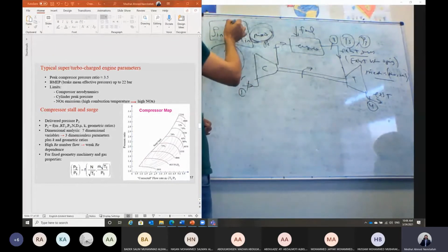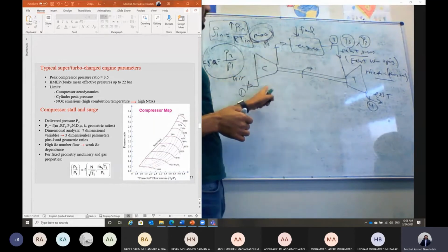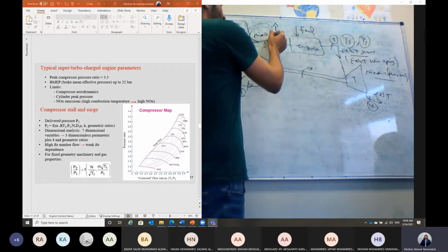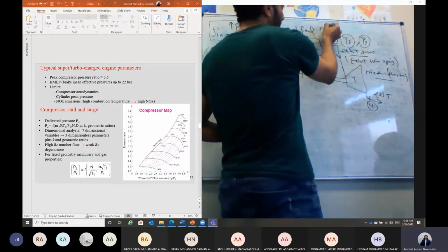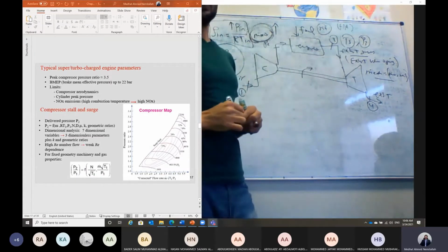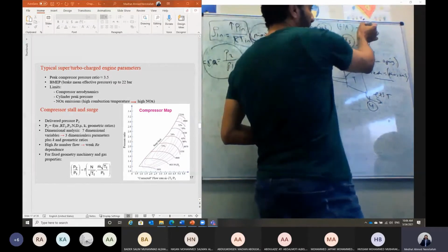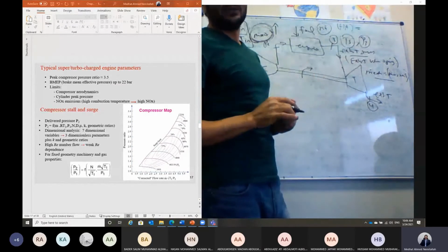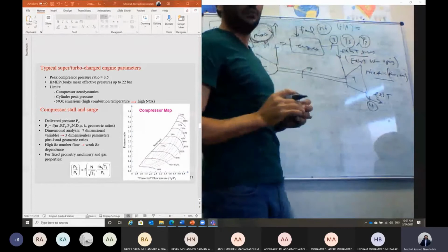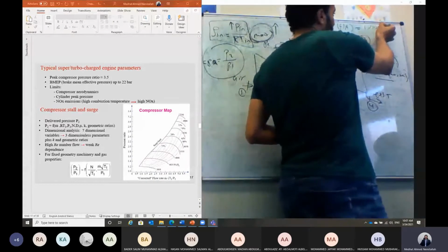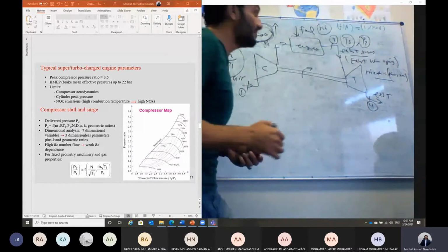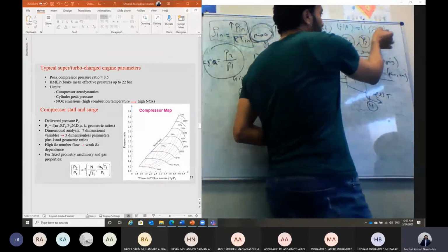So if we are able to raise the pressure at the intake manifold of the engine through the compressor, then in this case we can raise the mass flow rate of air. And based on this mass flow rate of air, the engine will decide the corresponding mass flow rate of fuel that will achieve a certain value of fuel to air ratio. We said that a gasoline engine, especially, is working almost at a stoichiometric condition, almost at lambda equal to 1. So the actual fuel to air ratio is almost fixed at all loads, at a ratio of 1 to 14.6. This is almost the fuel to air ratio for a gasoline engine under a stoichiometric condition, under lambda equal to 1.